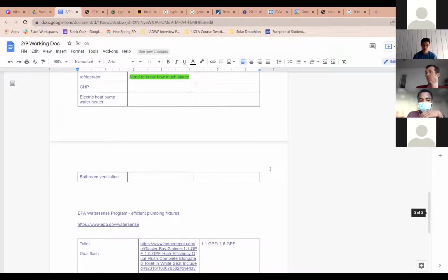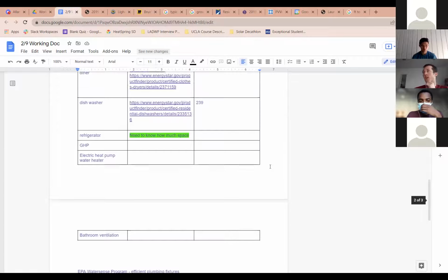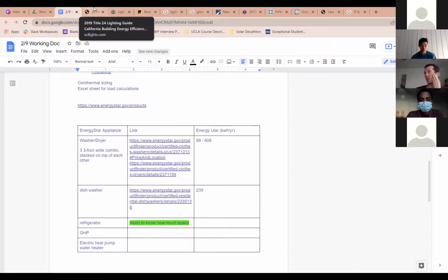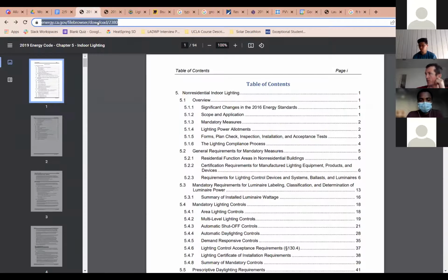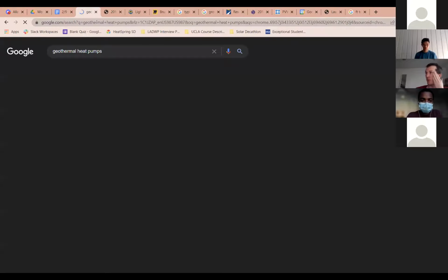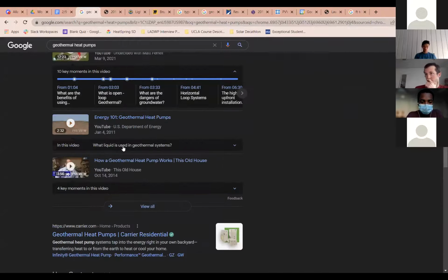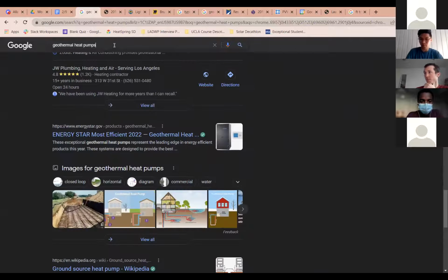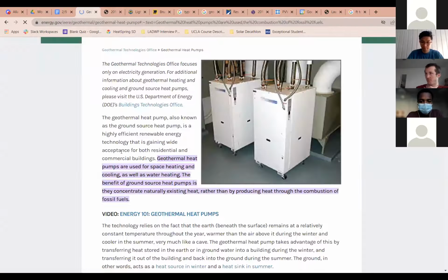All right. One note on the ground source heat pump. I think there are two types of systems for that. There are vertical shafts, and there are more horizontal systems. I know that the vertical ones are generally more expensive, but they use less space, whereas horizontal is shallower, so cheaper excavation, but you need the horizontal space. Right. So I assume this would probably be below the parking lot. Yeah. And I'm thinking that we would do the horizontal one, not the bore down, just because we have a bit of a larger area.